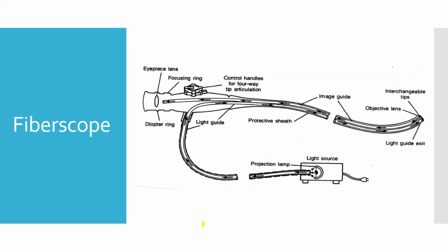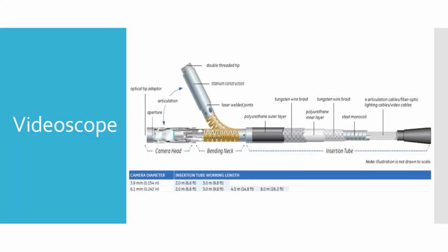If we look at a cutaway of a video scope, this is just the tip end of it. We all know what we get when we take a video camera and plug it into a TV. That's basically what you have at the control end. But the internals of a video scope look something like this. This one shows those four articulation cables, and then the fiber optic bundles. The construction of these is almost like a hydraulic hose, with multiple layers, braided layers of metal and rubber, and so they seal them. So hopefully you don't get contamination inside them, oil and grease and other stuff.